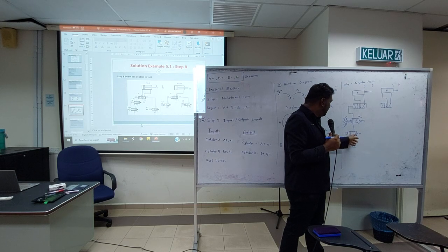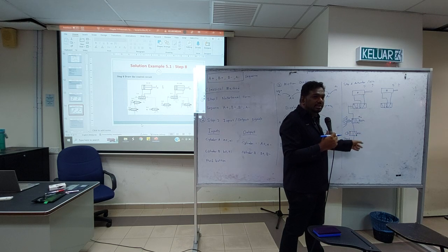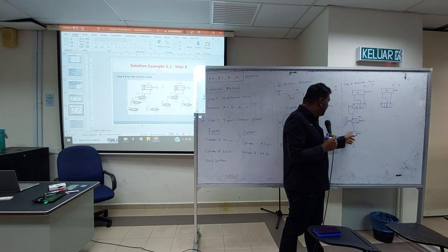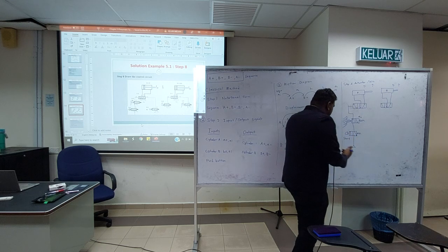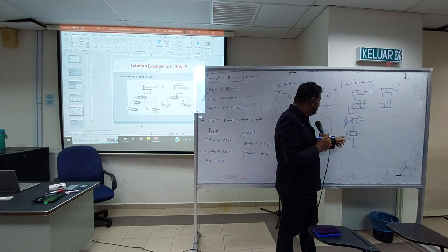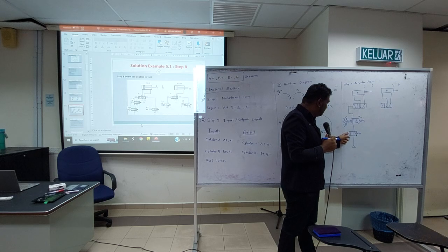And this is your working port connected to exhaust. So it is disconnected. But when you press the push button, what happens here? From here it will move to here. So the compressor goes to the working port, but only when you press. When you press, it will shift to this.